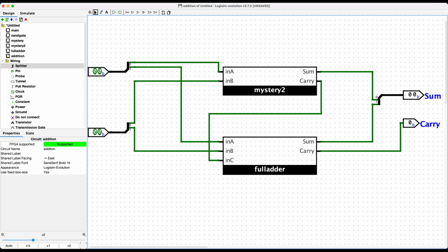Well, the C stands for carry, and remember we had a carry flag. So if I were to put 64 of these things together, what would happen to the 64th carry? I would use that to set the flag to 1 or 0 if I was doing one of the instructions that had an S at the end of it. Otherwise, I would ignore the flag.